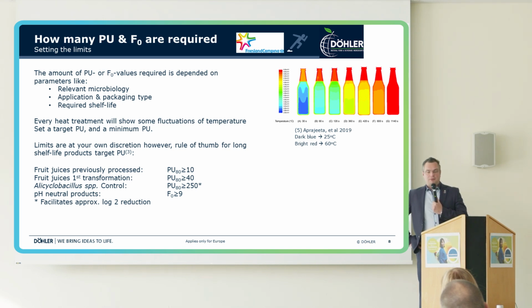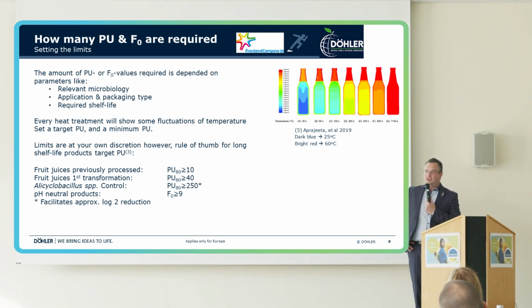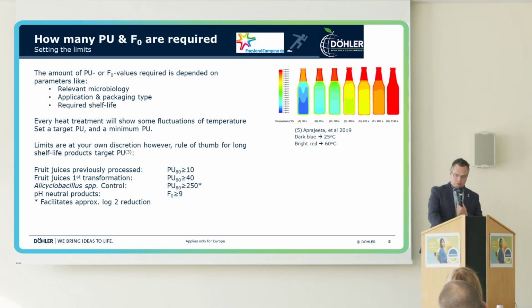Meaning that if you have an indirect bottle heat treatment through a tunnel heat exchanger, you really need to make sure that the temperature inside the bottle is homogeneous at your set point and not stop too early. However, the same thing counts for cooling it down. Now, the Bacillus can better be controlled by proper cooling down of your product than just by heat treatment alone.